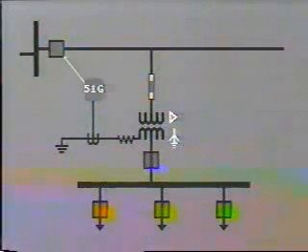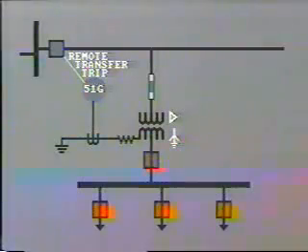One way of achieving this is to provide a communication channel between the relay and the breaker. This is known as a remote transfer trip signal, transmitted over power line carrier or on a telephone circuit or microwave circuit. This method is quite expensive, and special care needs to be taken with the installation so as to avoid interference from outside signals which may cause inadvertent tripping. Of course, on large, high-voltage transmission lines, this method is used extensively, but it is not so common on distribution systems.